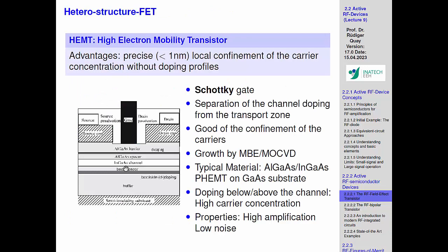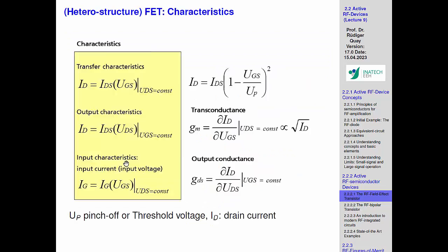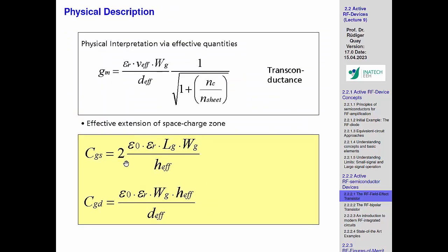I told you, people originally looked at gallium arsenide, and then they realized if they added another indium atom again in a very nice layer, then this effective velocity is just higher. That's why they came up with this idea. It has a lower effective mass, and it's also much more mobile, so it has better mobility. This is what you introduce by material selection.